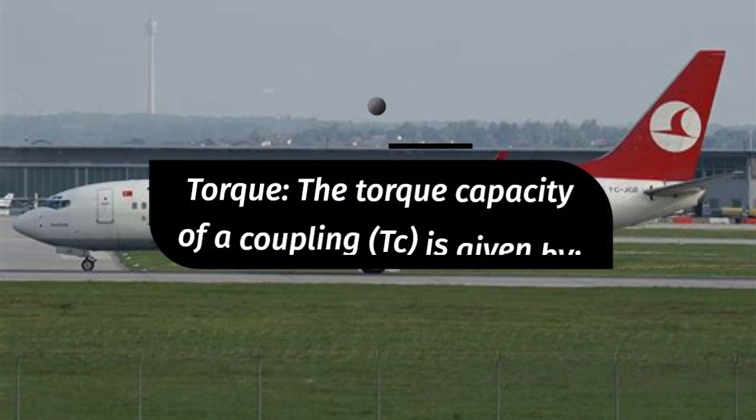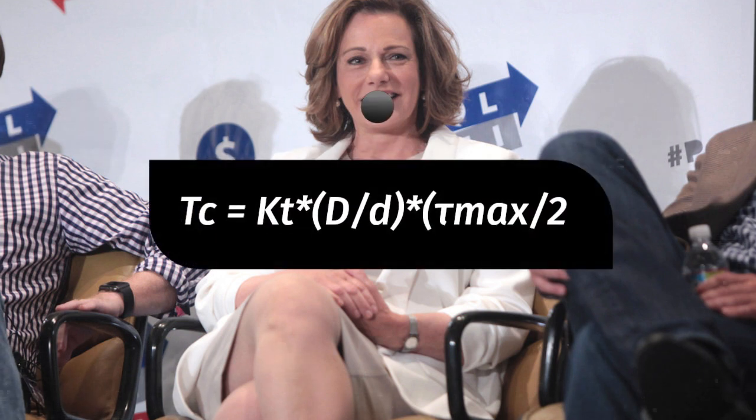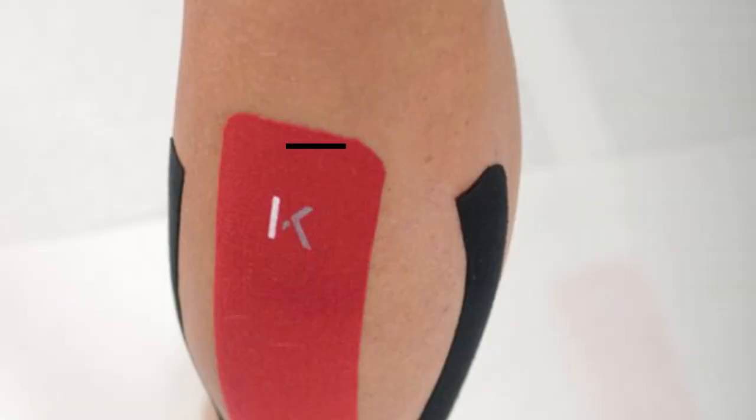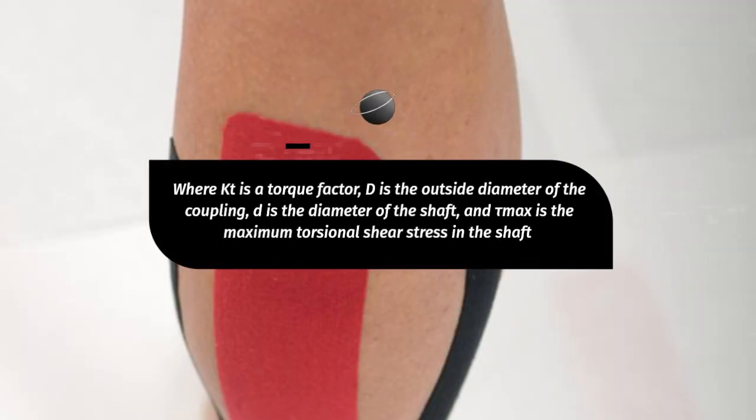Torque. The torque capacity of a coupling, Tc, is given by Tc equals Kt, D over d, tau max over 2, where Kt is a torque factor, D is the outside diameter of the coupling, d is the diameter of the shaft, and tau max is the maximum torsional shear stress in the shaft.